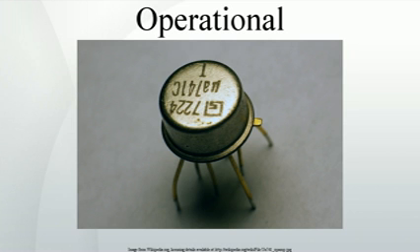A zero voltage level detector, V_REF equals 0, can convert, for example, the output of a sine wave from a function generator into a variable frequency square wave. If V_I is a sine wave, triangular wave, or wave of any other shape that is symmetrical around 0, the zero-crossing detector's output will be square. Zero-crossing detection may also be useful in triggering TRIACs at the best time to reduce mains interference and current spikes.